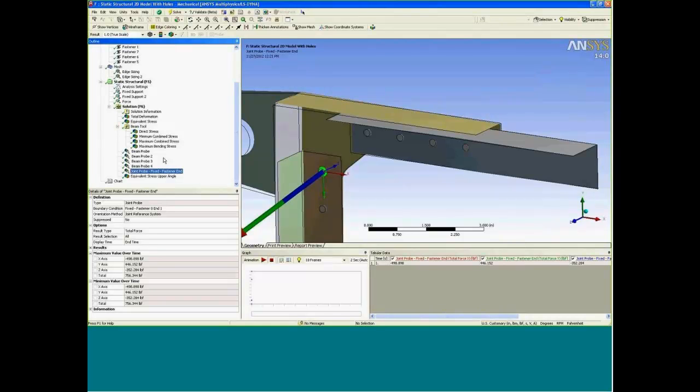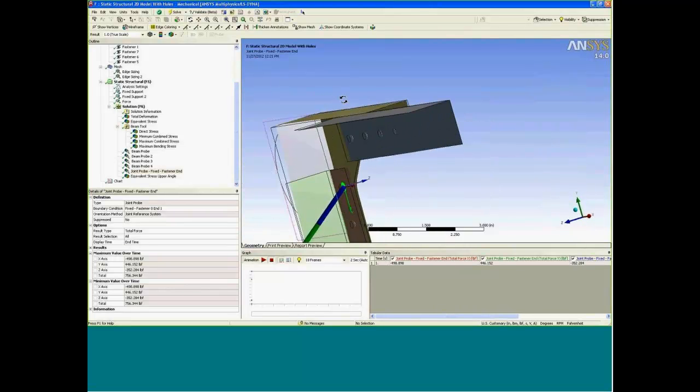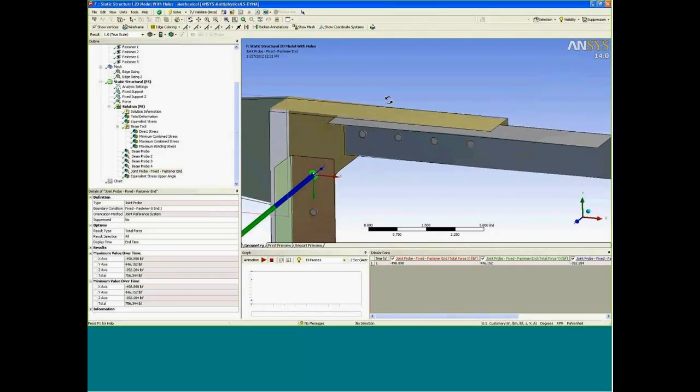One note here before we move on, this is just a quick note that this is kind of an upper level loads modeling procedure. In this example, I don't have any body-to-body contact. However, this is more or less just a linear model. If you're using shell elements, you can include body-to-body contact with the shell offset due to the thickness of each shell.